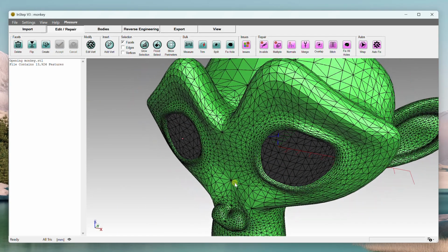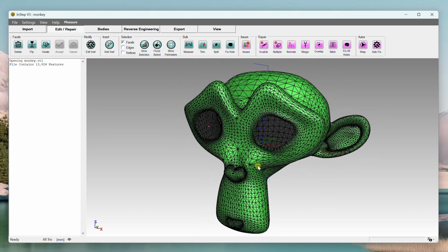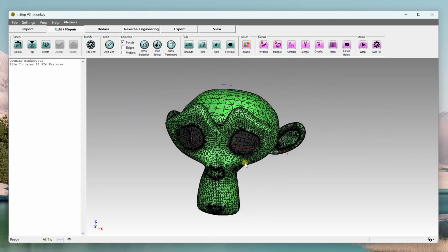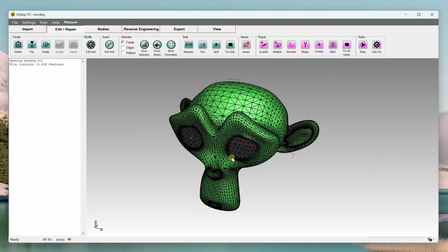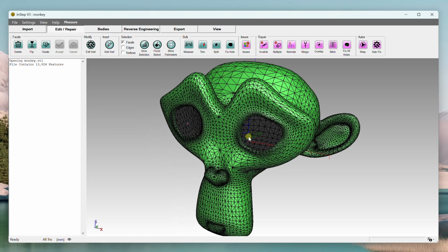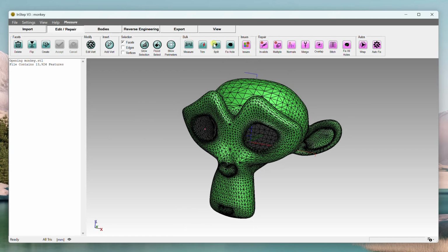And also for people that work with this on very large and very complicated models, or ones that have a lot of changes that need to be applied, my recommendation is you import it, you make small changes or even big changes if you need to, and then occasionally you save as a backup. And when I say save as a backup, there is no internal format that will expedite this. This is really based around the STL format.